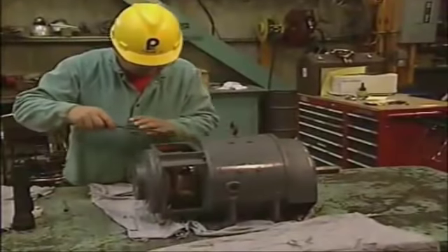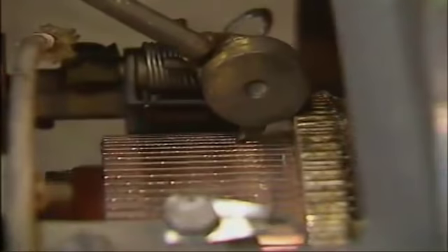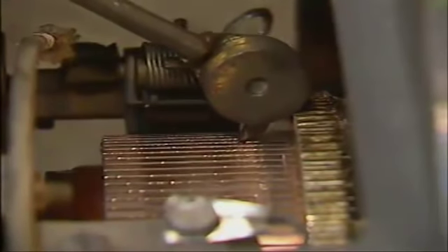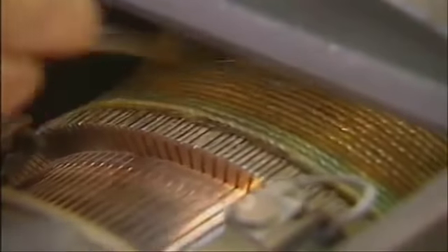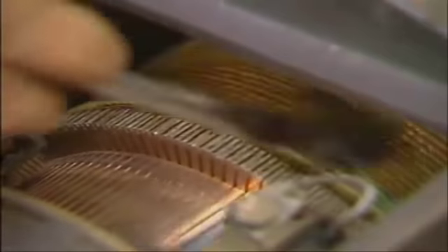between the segments. In addition, hand slotters or scrapers are tools specifically designed to remove excess mica and foreign particles and to smooth the edges of the commutator segments. The bearing end of the commutator and the area behind the risers should also be cleaned until all dirt and dust are removed.